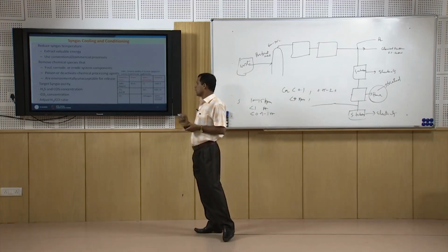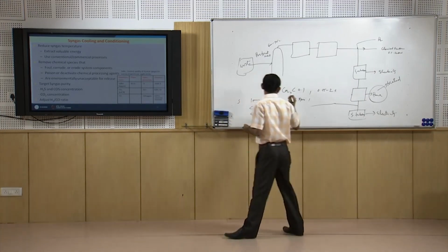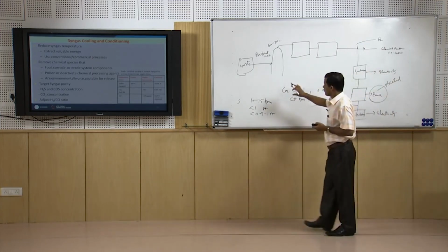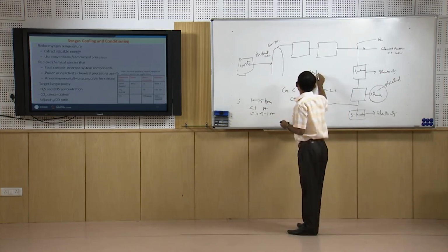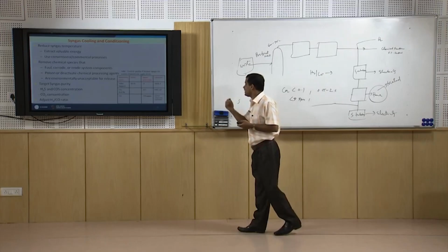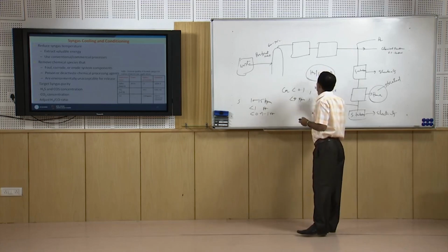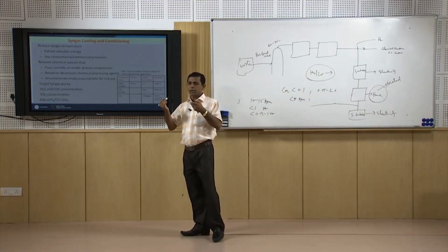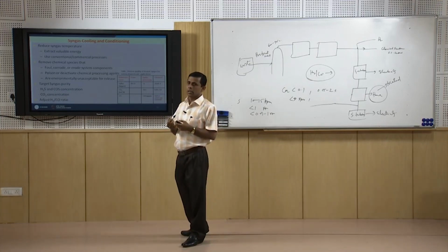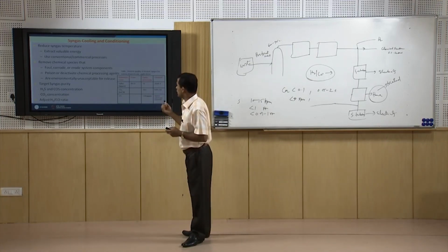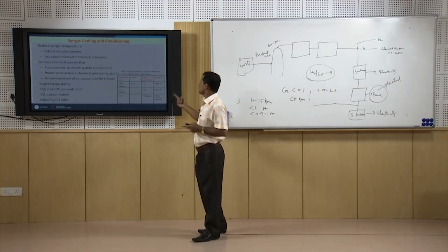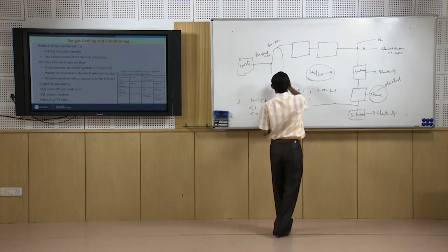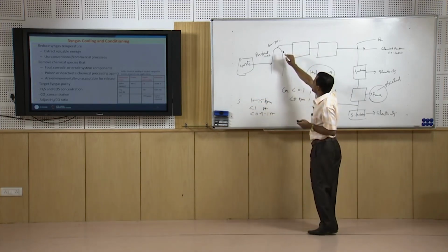So, depending upon the nature of the chemicals we are going to produce, the H2/CO ratio is required. To maintain this ratio we need to condition the syngas, that means some other reactions are carried out with the syngas to adjust the H2/CO ratio, and cooling is required because the syngas will be at very high temperature, as I have mentioned.